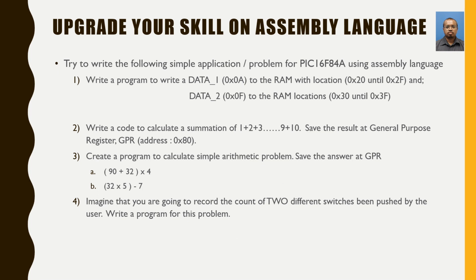Right, finally towards the end of the chapter, for now you have all the skills that you have learned before. So try to write the following simple application, just to see whether or not you are able to understand what we have learned so far. First of all, you have to write a program to write data 0x0A to the RAM address location 0x20 until 2F. Okay, this requires repetition, whereby you have to do some looping. And then the data 0x0F to RAM locations 0x30 until 0x3F.